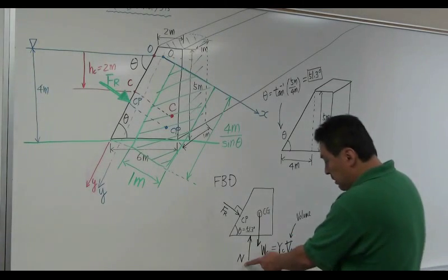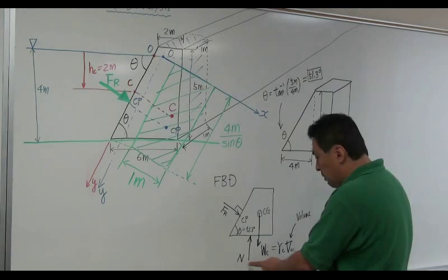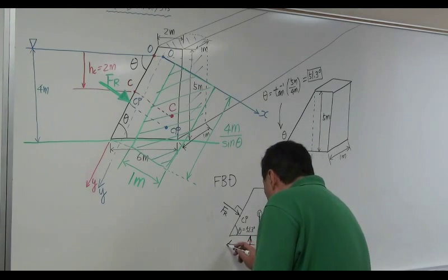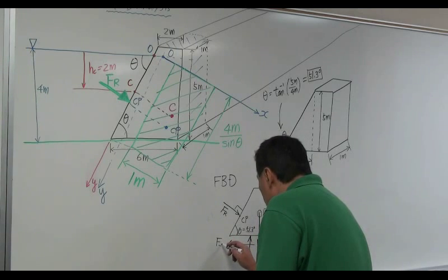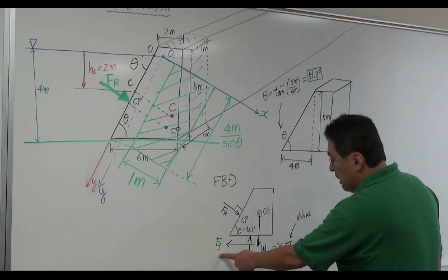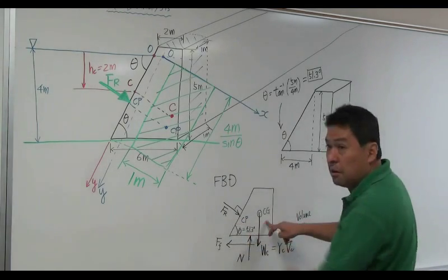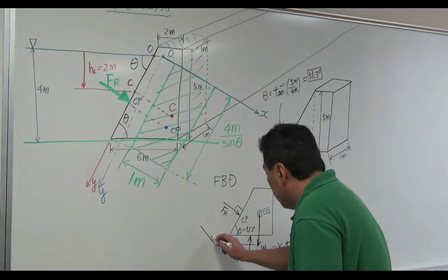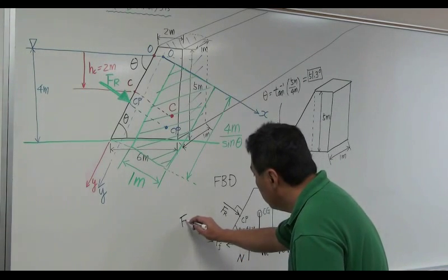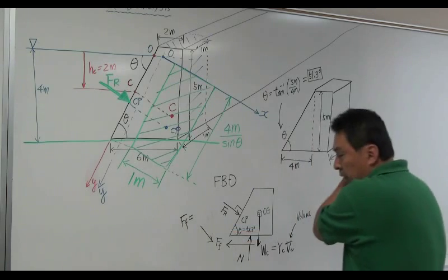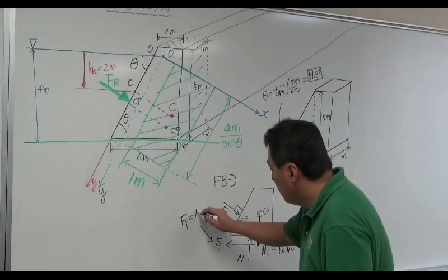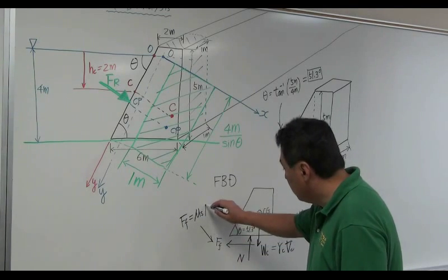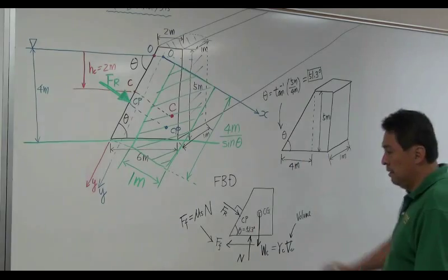And because of this normal reaction force, you're also going to develop a force due to friction. Force due to friction is the force trying to prevent this concrete from sliding against this applied force. The magnitude of it is going to be determined by the static friction coefficient, mu s, multiplied by how big your reaction force is.